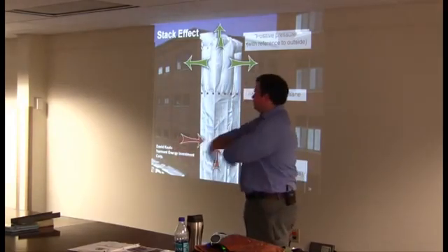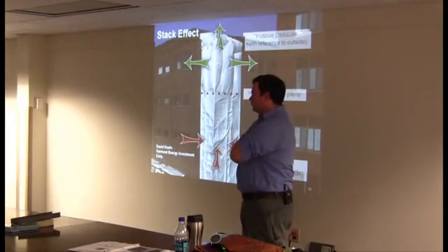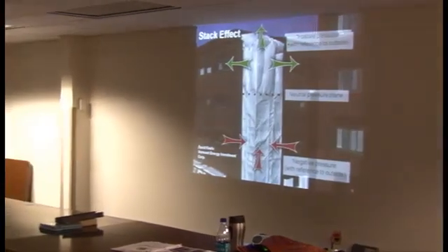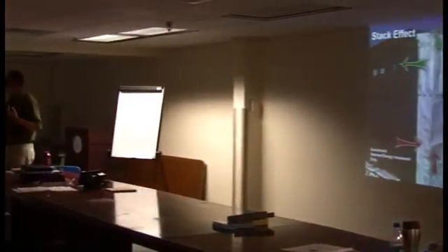So like Burke said, it's a function of the height of the building. It's also a function of the temperature between the inside and the outside. So you tend to see more stack effect in the wintertime. It's colder, there's a bigger temperature difference.